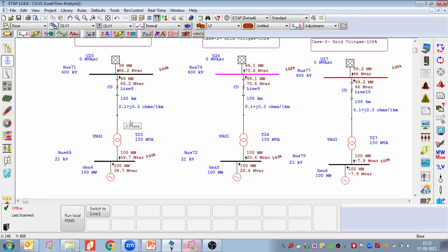In case 3, the generator bus terminal voltage is varying, sir. It is 100%. This is 100%. Yes, the generator wants to keep the terminal voltage constant, and accordingly the reactive power has Qmax and Q minimum limits. Accordingly, they will adjust the maximum and minimum reactive power, adjusting to this constant bus voltage. It was originally because the receiving end voltage is high.